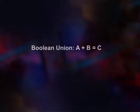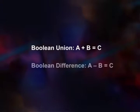Boolean union: A plus B equals C. The two objects selected will be combined into a single object. All of the objects' internally overlapping sections will be deleted. Boolean difference: A minus B equals C. The second object that you select will be subtracted from the first object. This is a very useful tool for creating holes in an object.